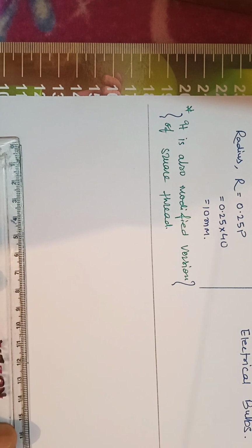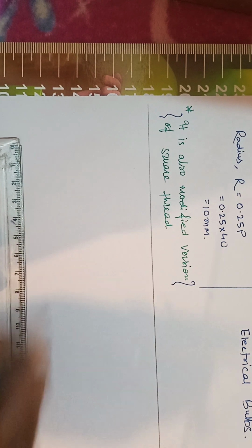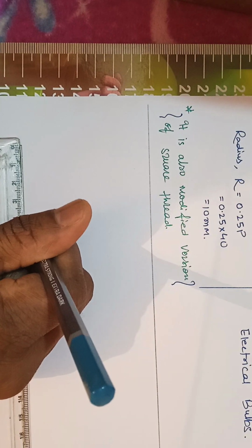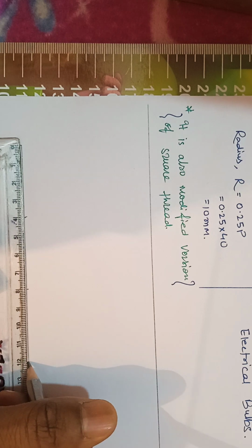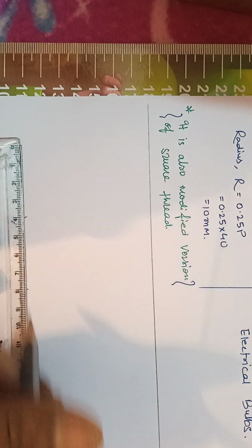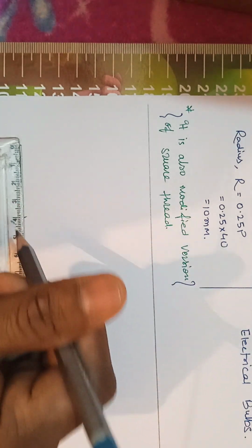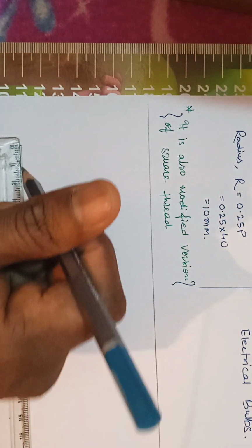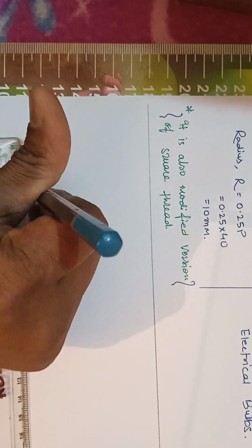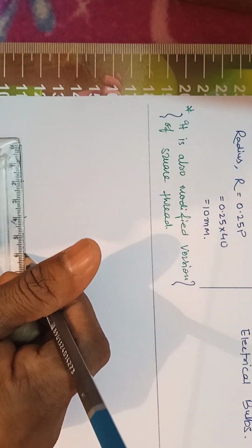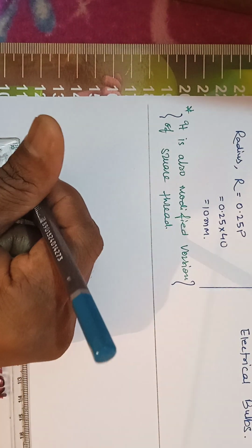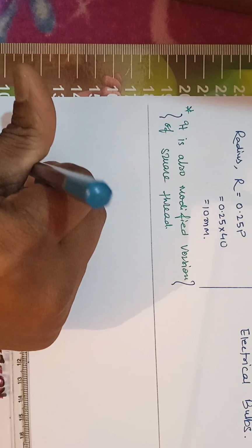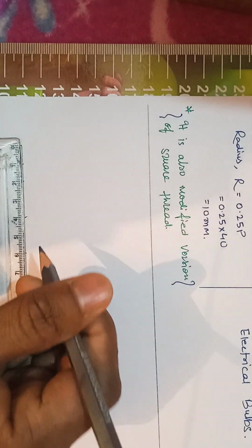At a gap of 4 centimeters or 40 mm, we will mark first, that is the pitch of the thread. When marking this pitch of 40 mm each, at the same time we will mark the midpoints, that is at 20. So 20 over here, again 20 over here, and again we have further marked 10, because the radius that we calculated is 10 mm.